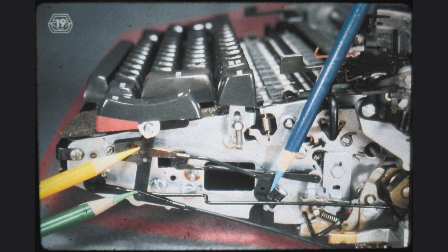Another possible lock for the character keys on the keyboard is the on-off switch. The green pencil points at a link which holds the on-off key in its position. With the movement of the link pointed out by the yellow pencil, we are able to rotate the clamp fastened to a bail called the keyboard lock bail, indicated by the blue pencil. Notice that when you turn the on-off switch to on, the lockout bail turns top towards the front.